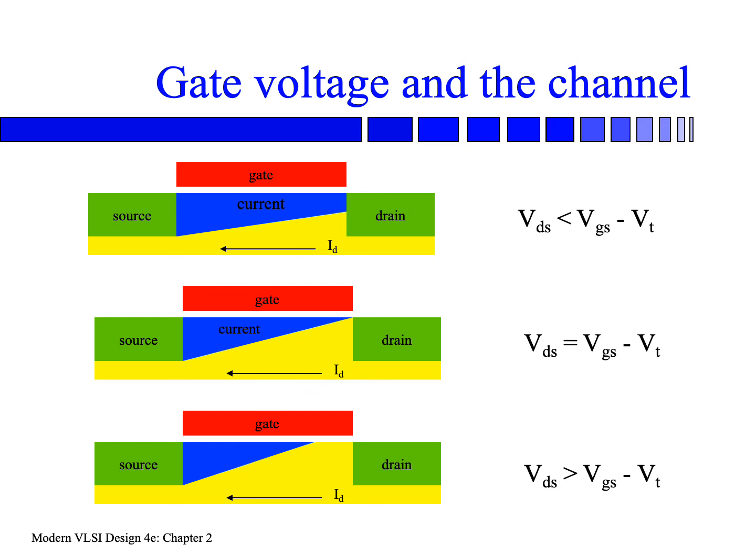Of course, you have this kind of shape because the drain voltage is a little bit higher than the source, but not high enough. Remember, they are still smaller than VGS minus VT. So the current will flow from the drain to the source.